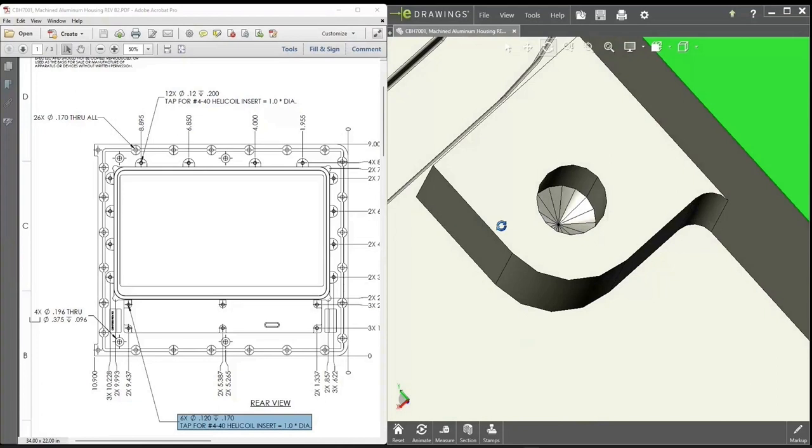And being that it's not a flat bottom, the question we would have is whether or not that is required, or whether or not we can modify that and make it a flat bottom. For the DFM, we would want to consider milling the hole instead of drilling the hole, and then thread milling the threads rather than using a tap. And that would be something to consider to create efficiency at the production quantity. I mean, all these details are very important for the DFM.